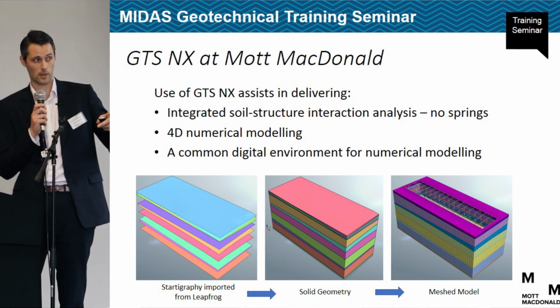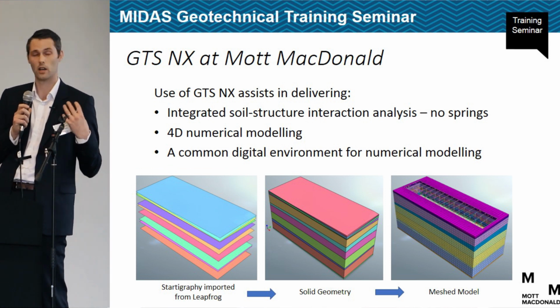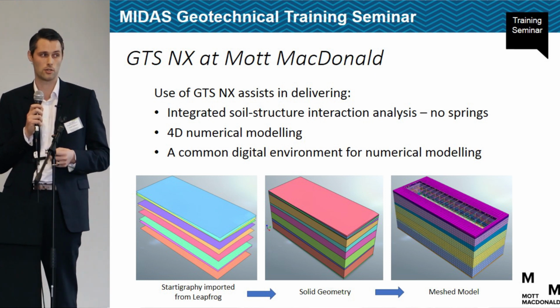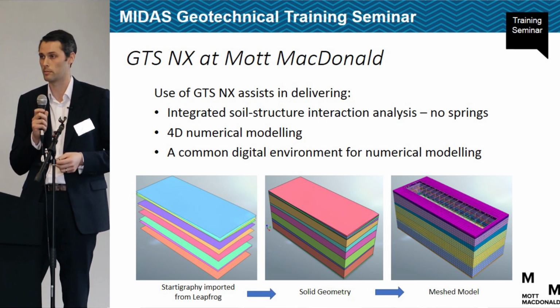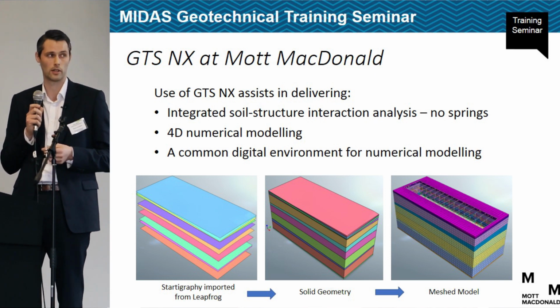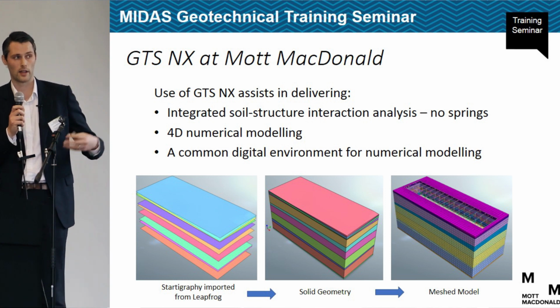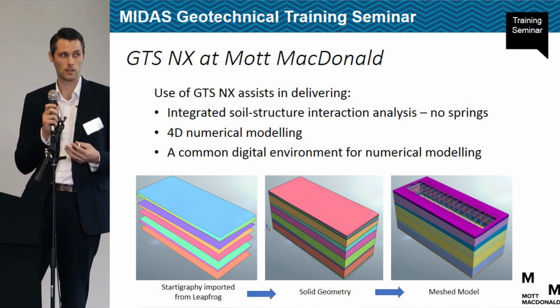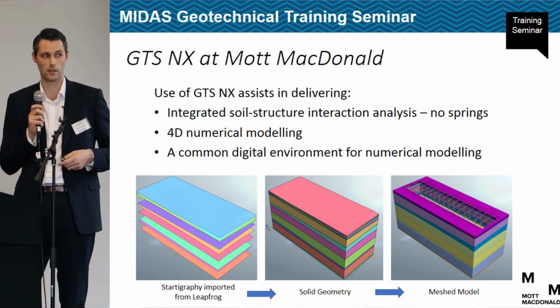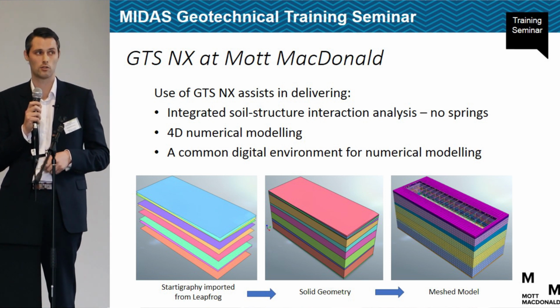So at the bottom, there's an example just where we've imported non-planar ground stratigraphy from a software called Leapfrog, which is a tool we use for modelling complex geological sequences. Import that into Midas GTS NX, chop up our solid geometry, and then from there go ahead with meshing to have our structure within it.